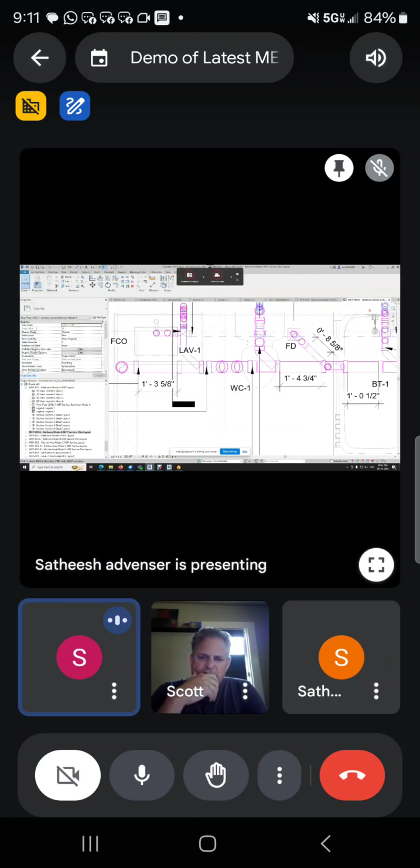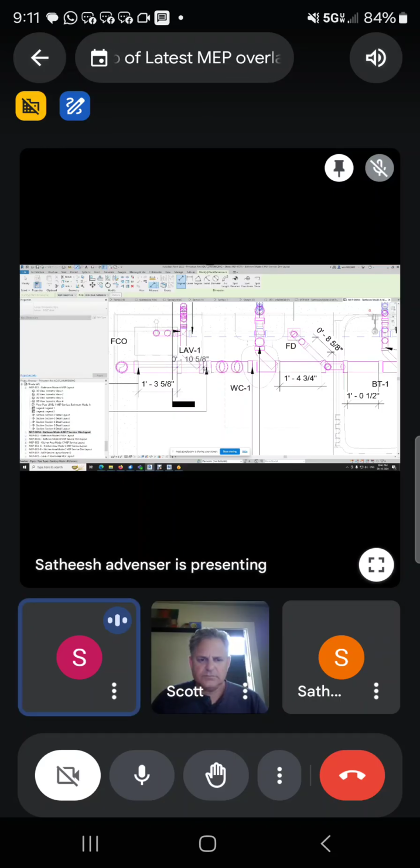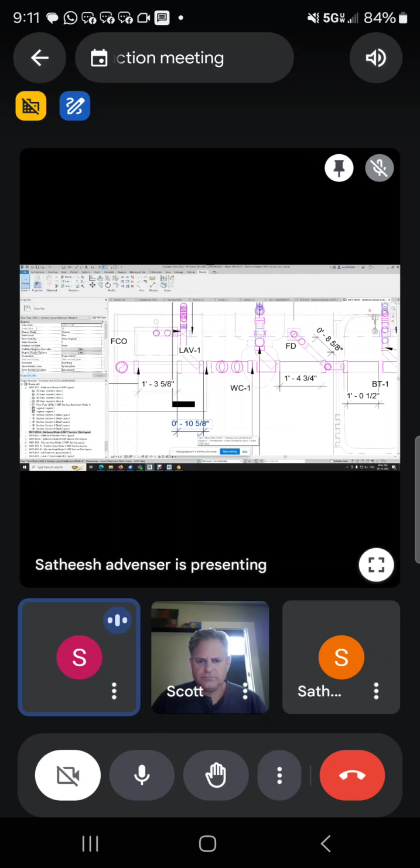Can we create some sort of generic table that a flange should be 1/2 and 1/2 added on top of it? That way these guys already have those directives and add them into the drawing itself, because we've given them that delta variance for a flange, and then maybe there might be a longer pipe. You can give them the deltas, and they can incorporate that into their drawing and measurements.